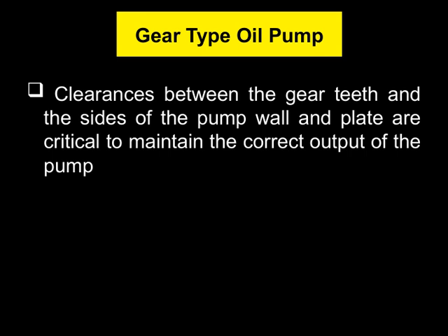It's particularly important in gear-type oil pumps, where precise clearances ensure that the pump maintains the right pressure and volume. Proper clearances help in achieving optimal performance, preventing leaks, and extending the lifespan of the pump. So, when designing or maintaining these pumps, always pay close attention to these gaps. They are key to ensuring the pump functions reliably and efficiently over time. This focus on clearances ties back to our overall goal of achieving a well-maintained, high-performing hydraulic system.